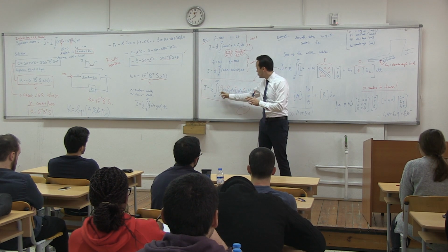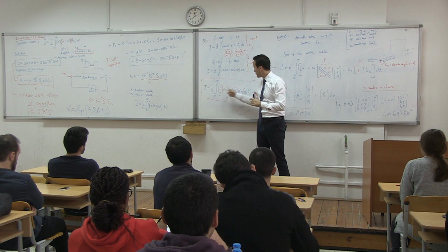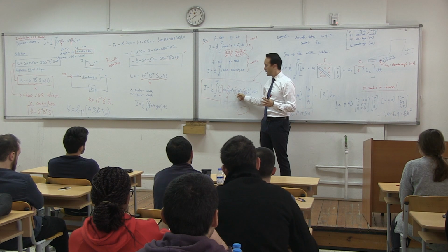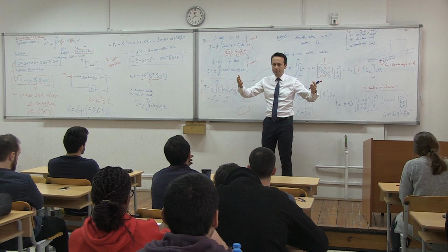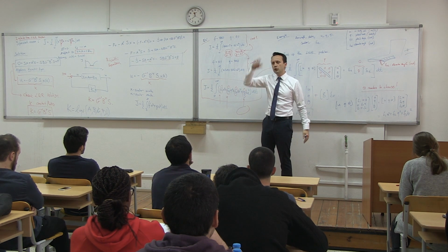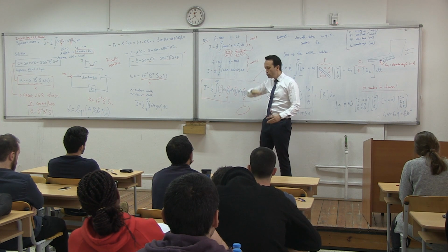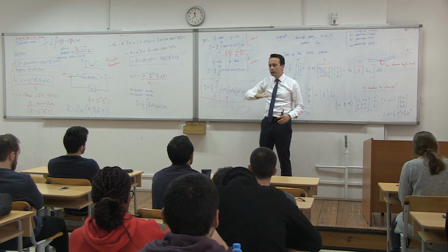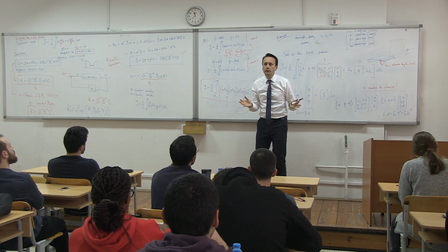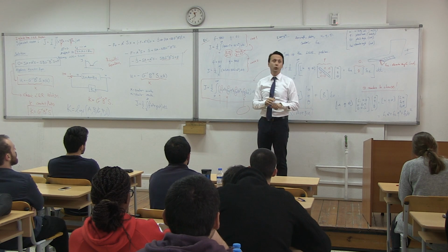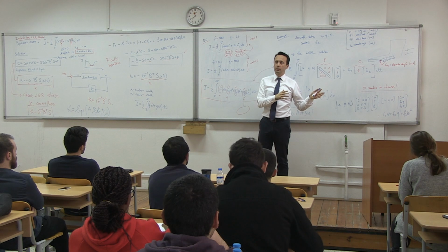Saying that U and theta will only change if Q is changing. Therefore, the most important one is Q. Don't put much emphasis on these two, and make them somewhat comparable. And then I would look at the outcome. If U is moving too much, I would probably increase this one a little bit, reduce this one a little bit, and then Q and this del E will move somewhat little, and this one move comparable, and then have a good controller. And then I would go back and say, okay, where did I move the closed loop eigenvalues?